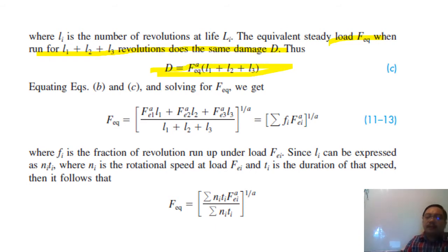Why does it say damage? The book uses the word damage because eventually you have to change things. For example, the nearest example to you is your car or your motorcycle. You have to do maintenance. After a certain period of time, you have to change the lubricant, the oil, the bearing and everything. You have to change the timing belt, the timing chain and everything. And what indicator shows that the bearing has come to the end of its life? The indicator is the life itself.